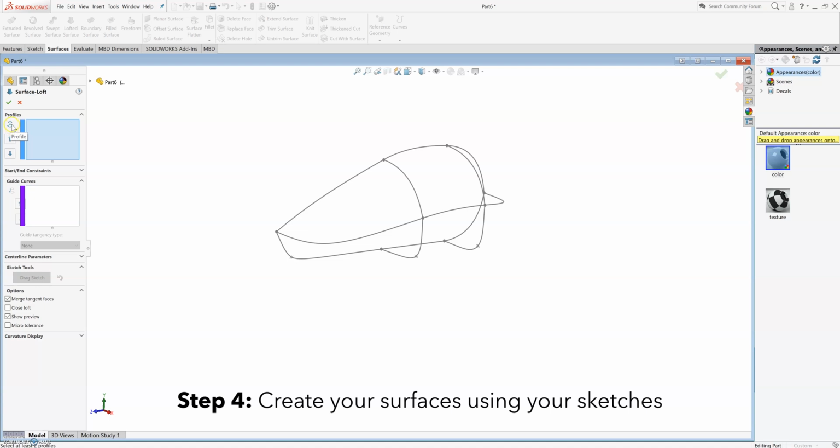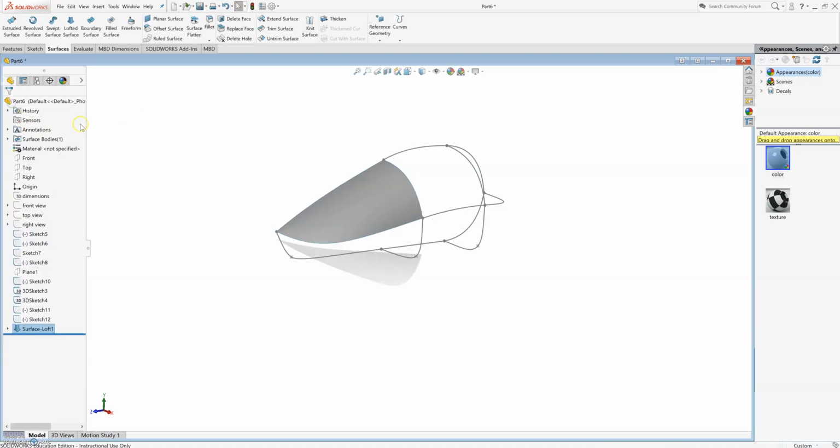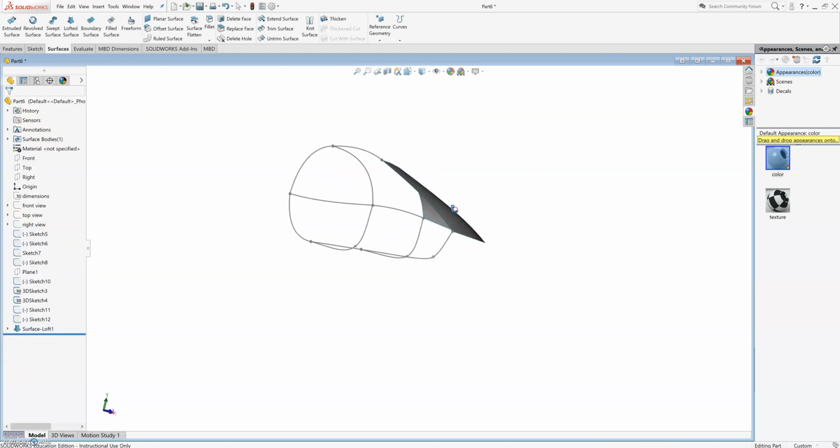It's very similar. I'm going to loft this line to this line. I'm clicking close to the same point so that these green dots fall along the same path. You don't want your surface twisting, which might happen in this case. So just click close to the same endpoint. And then the guide curve I'm going to use is this line. Great, so this is our first surface.